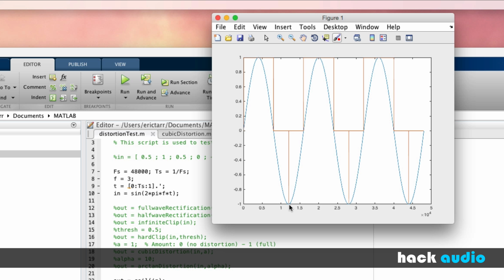For our purpose, we're going to ignore this when we think about the number of possible amplitude levels there are. We're going to think about our input signal, making sure that it stays within this range of -1 to 1, and that it's very rarely actually going to have this amplitude. So for us, this kind of processing with our ceiling function will produce a signal that has 2 amplitude levels, 0 and 1. This is equivalent to what happens when we work with 1-bit audio. 1 bit can either have 0 or 1, and that's 2 amplitude levels.